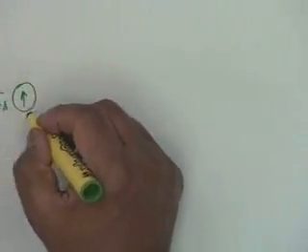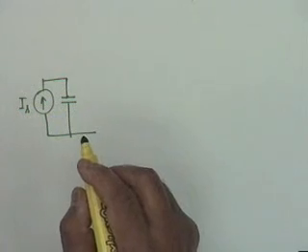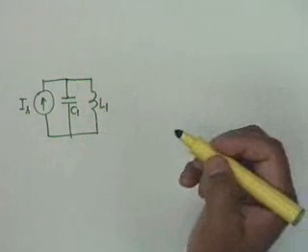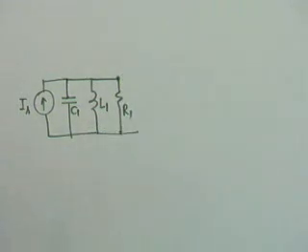The final problem is that of a synchronously tuned amplifier, and we shall assume that we have only two stages of synchronous tuning. In other words, we have two resonant circuits which resonate at the same frequency and their bandwidths are the same. One of the very simple ways of making this is to have two transistors. For simplicity, let us assume that perfect coils are available. If they are not, then you have to convert them into L in parallel with RP. So let's assume that we have perfect coils like this, or coils whose resistance has been taken into account, and we'll introduce a resistance R1 here.